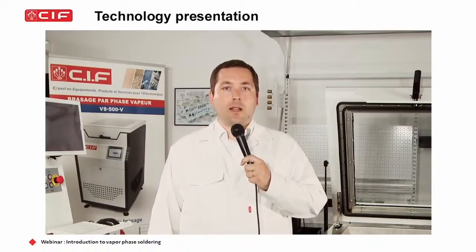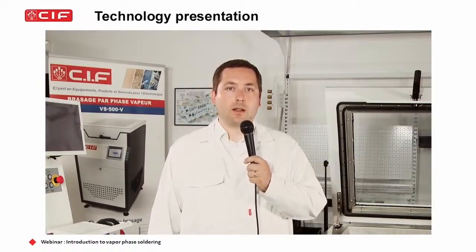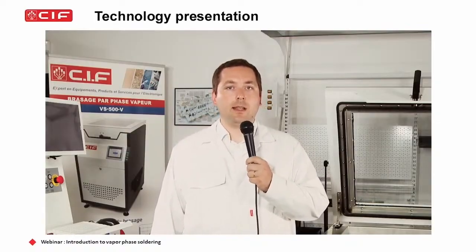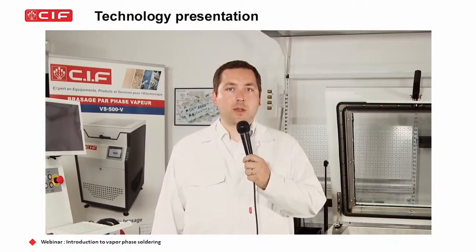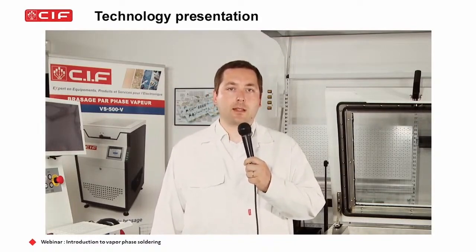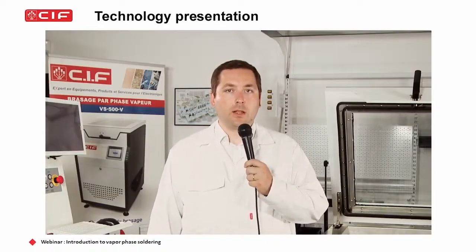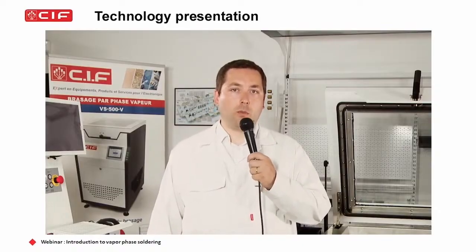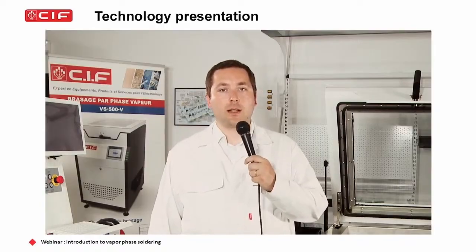The fifth advantage that we can now talk about is that this process is really easy to use. It means the process does not require specific settings for every board design, as you can usually do with conventional ovens. It means you are able to mix in the same batch different boards with different shapes and different designs, and they will be successfully soldered.